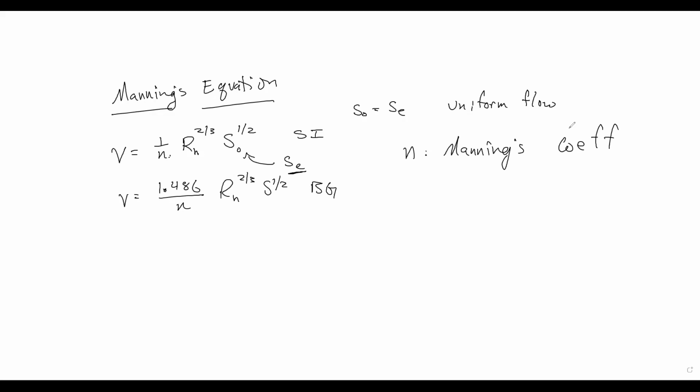Right now at our stage, it's a necessary evil. I don't like it because it changes with flow depth, just like the f changes with the Reynolds number, right? Your friction factor. Manning's is very similar. You can imagine if you have this relative roughness, so we've got cobbles on a riverbed and we have low flow, then this roughness height relative to the overall depth, if this is our e and this is our d, e over d is going to be relatively small.